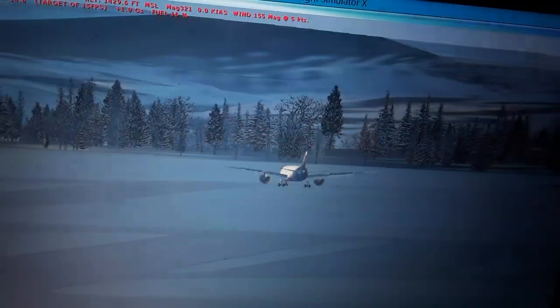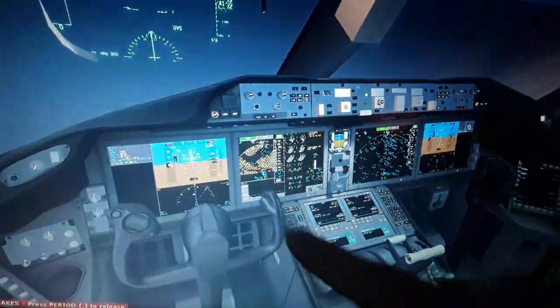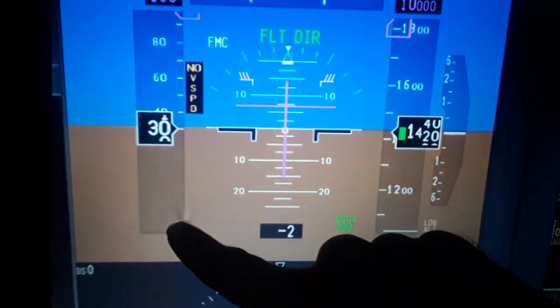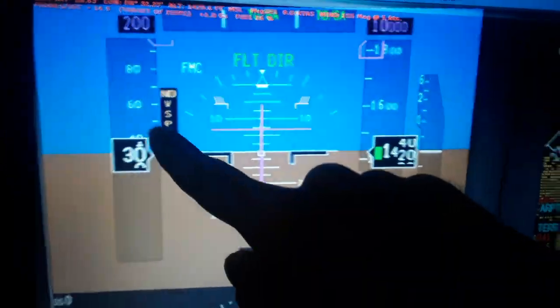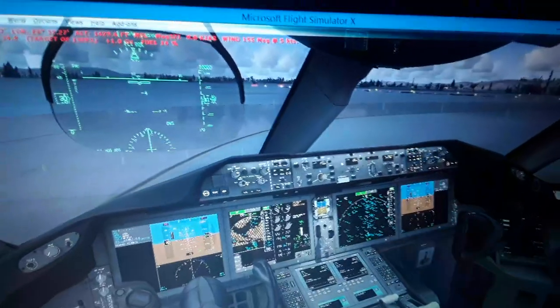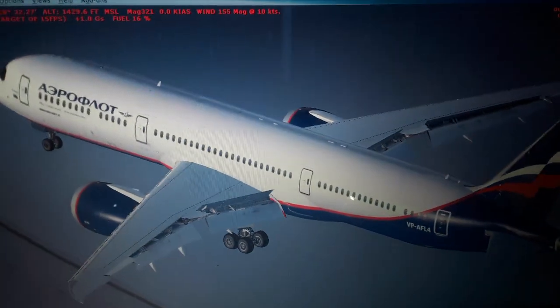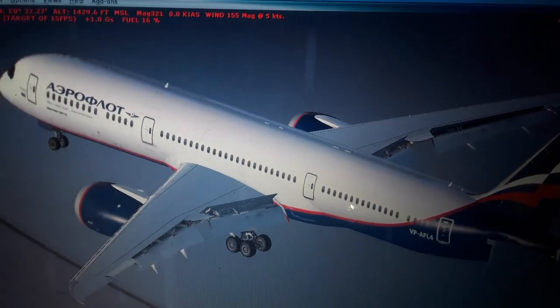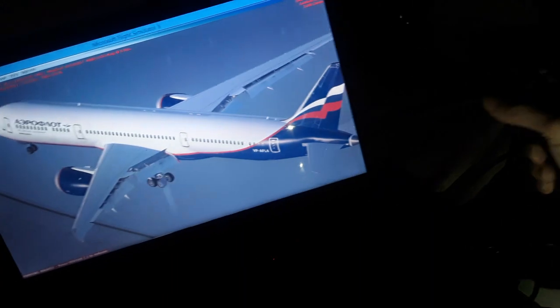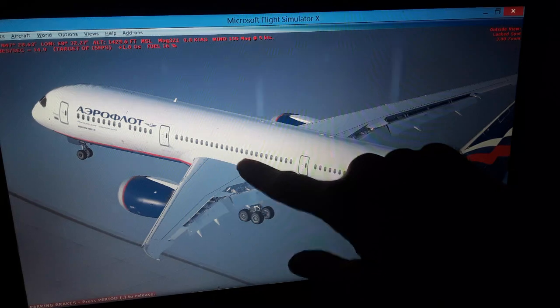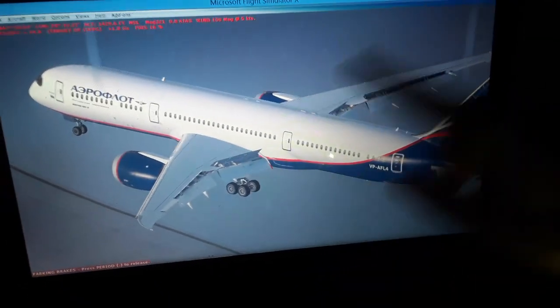So we need to monitor over here the stall speed. You will see the airspeed of the aircraft when we fly, and we have also the stall speed for a given angle of attack. You'll see the yellow and the red indication down here below the airspeed when you fly. We need to have an airspeed always above the stall speed. So the stall will develop behind here mainly. We have also the deflections, as you see the flight controls. So here is also the mean aerodynamic chord position. It's pretty much where the center of gravity, the vertical axis, will be located.